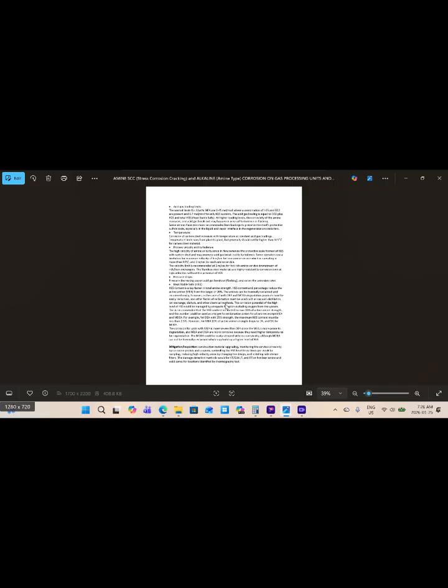Heat stable salts reduce the active amine MEA from the target of 20%. Amines can be thermally reclaimed and recovered easily. However, in the case of both DEA and MDEA, degradation products are hard to reclaim, and other forms of reclamation must be used, such as vacuum distillation, ion exchange and other chemical methods.